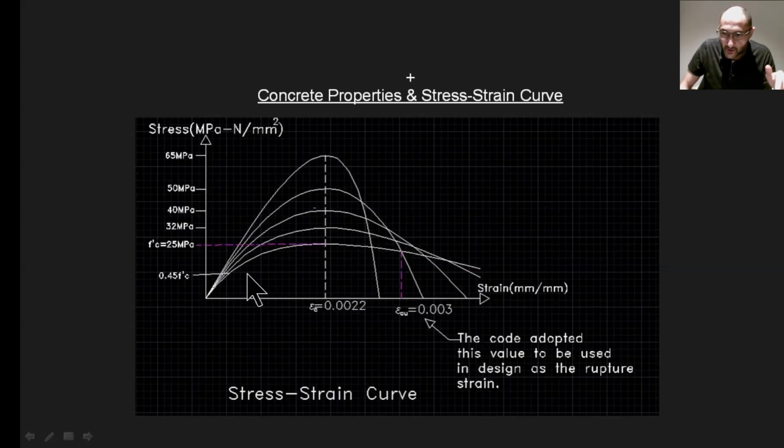On this general diagram here, the vertical axis represents the compressive stress or strength of the concrete, while the horizontal axis represents the strain, which is the deformation experienced under the applied loads. Now, this applied load from the CTM is typically controlled and increased gradually. The resulting stress-strain curve is unique for each concrete mix, and it varies based on the compressive strength f'c. So you can see here we have different curves for different strengths.